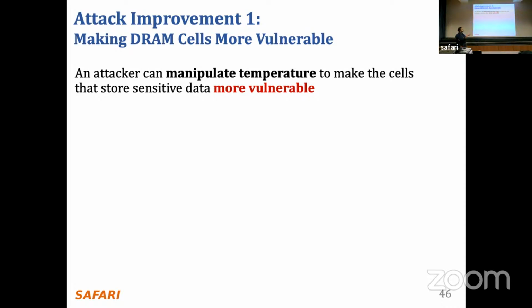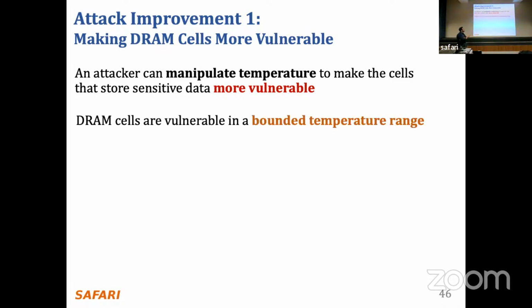Let's say you have a malicious employee in a data center that can heat up the chip, or maybe you have some chip with processing-in-memory enabled. You can pressurize that chip, put more workload, increase the temperature of the chip, and you can make that chip more vulnerable to RowHammer than the nominal voltage, not voltage, temperature.